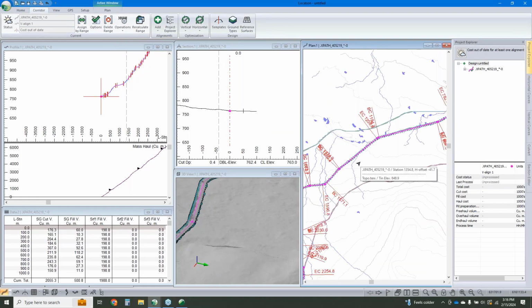All right, perfect. So I guess I'll set up the example that we're going to look at with the haul road. When we run an optimization, we're looking to minimize the road costs through Earthworks. And for the in-pit example, where we're dealing with a pit ramp, we don't necessarily want to minimize our Earthworks. We want to more or less just work around the existing mine infrastructure and also set things up to develop the mine. So we're less concerned with minimizing the actual excavation involved because it's all going to get dug out of there. So in that case, we're going to manually choose the location where we put things.